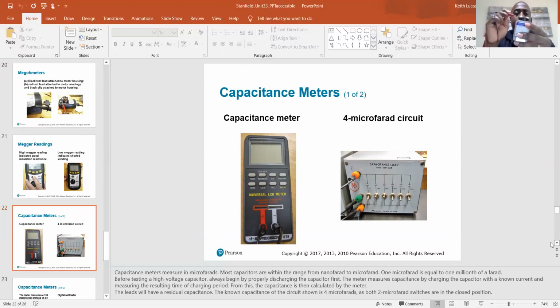I don't know how easy or difficult it is to tell, but this surface down here at the top is bubbled out. It's convex. So that's always a bad sign. When you see that on the capacitor, you know you've got a bad capacitor. So it should have read 7.5 microfarads. It read nothing because it is a bad capacitor. But yeah, that's how you want to check it.